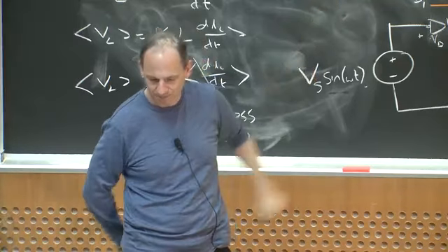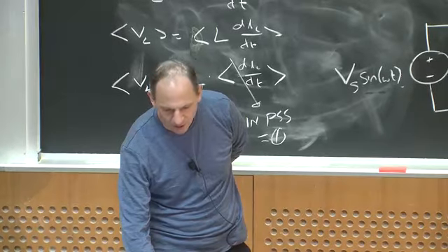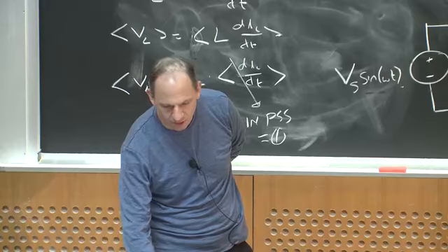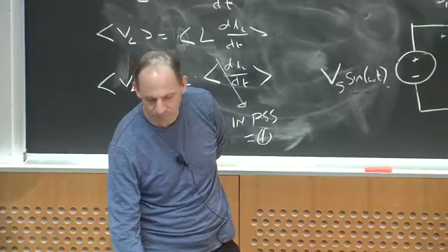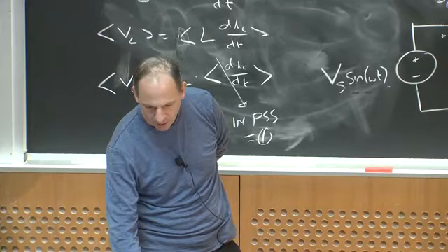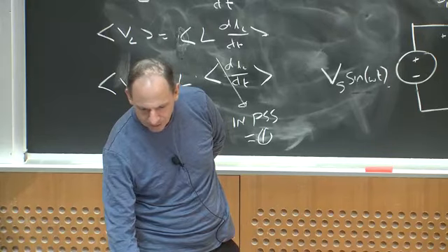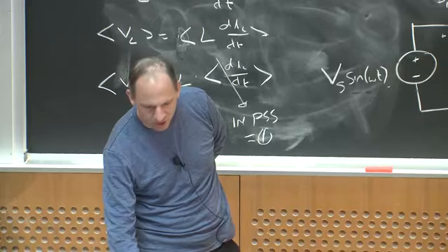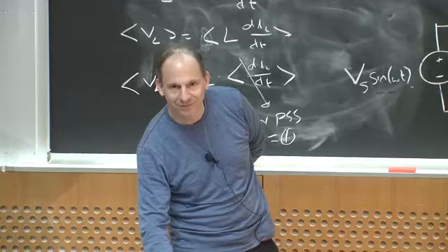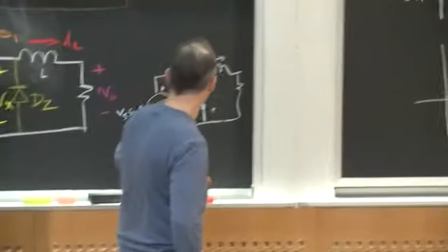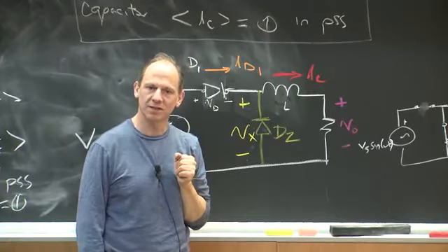And the interesting thing is, if I look at this, the inductor current's almost constant. Vx is exactly this half-wave rectified waveform. If I look at the output voltage here, it is almost constant, and it's just about 1/3, or 1 over pi, times the peak value of the sine wave, right? So we've been able to use the fact that I understand the average value across the inductor to tell us what the output voltage of this thing is going to be in periodic steady state.